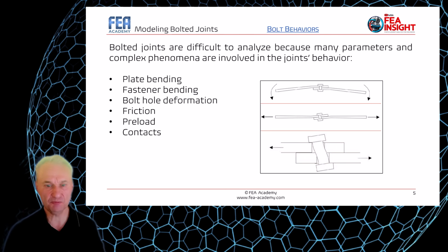So it is also important to mention that a few years ago, analyzing a joint was problematic for the finite element process in terms of modeling time, because each fastener has to be modeled by one or several elements. Okay? However, with the modern FEA packages, the process is much easier and we can now model each fastener rapidly in a complex joint. And I'm going to show you how we can do that.